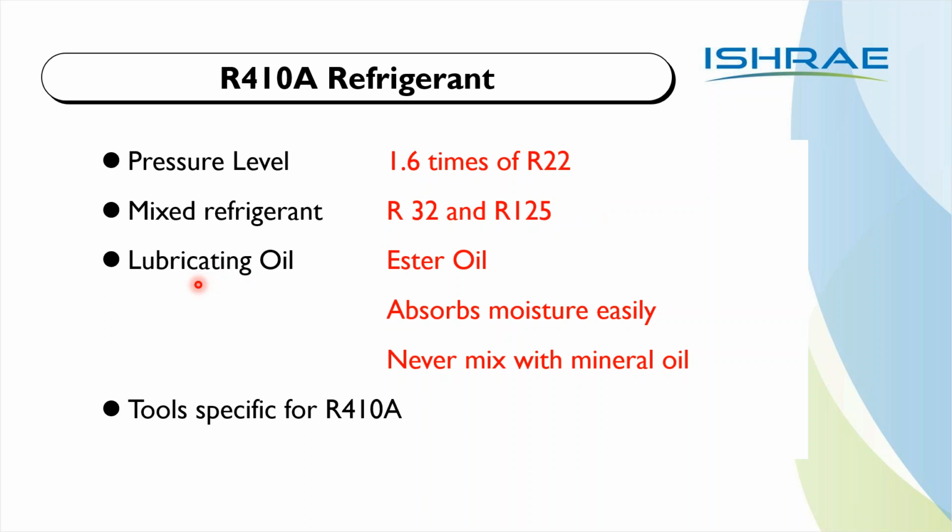So the type of lubricating oil that you need to use is an ester oil. It absorbs moisture easily. Never mix with mineral oil. Do not use the same oil that you use for R22 refrigerant. You have to use ester-based oil.